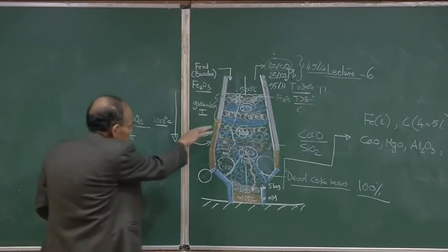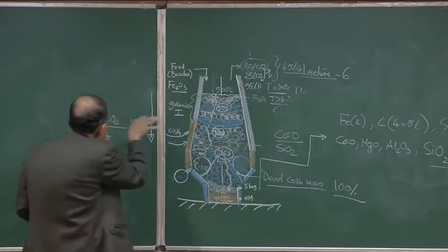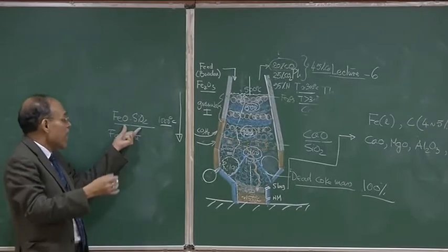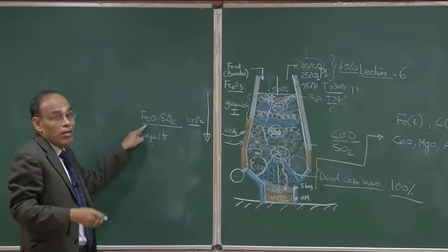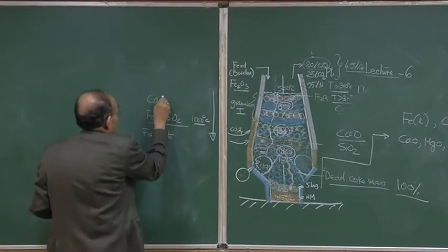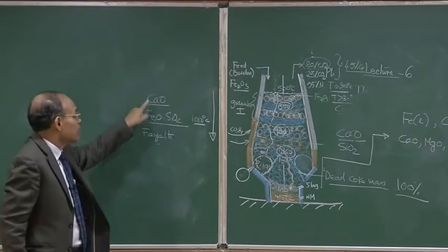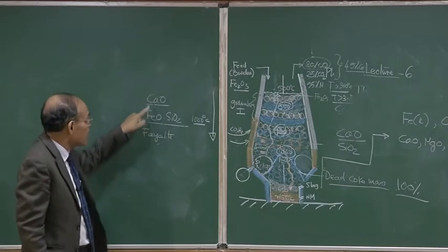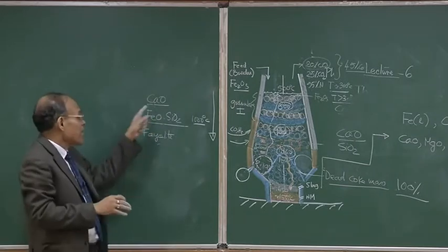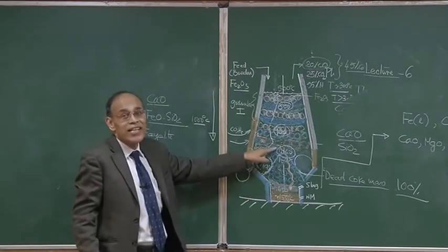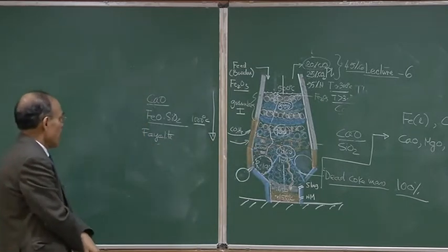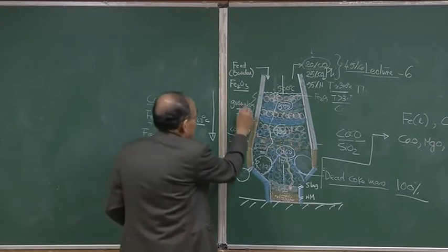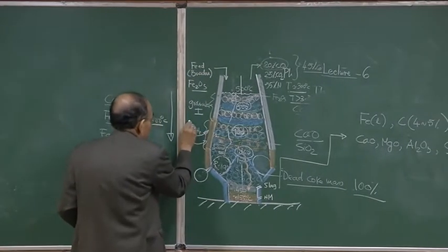And now with further temperature increase, as it descends further, the proportion of this is increased, and also the lime now becomes active. Lime starts to become soft, and lime is a strong basic oxide, and it has a great affinity towards FeO. Then the lime tries to replace FeO, and the moment lime is able to replace FeO, that FeO will undergo instantaneous reduction, because the temperature is extremely high. So, we have a granular zone, and then we have a cohesive zone.